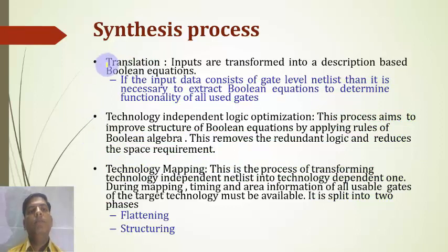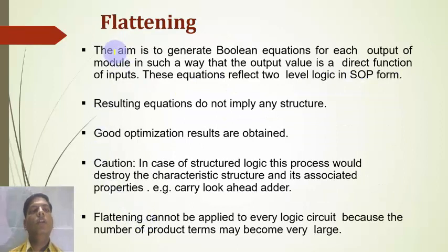Synthesis process: translation, technology independent logic optimization, and technology mapping. In that, flattening and structuring are there. So first we will go towards flattening. Flattening means the aim is to generate Boolean equations for each output of a module